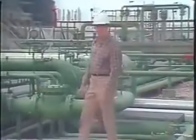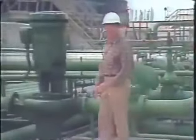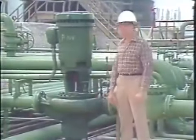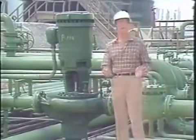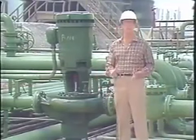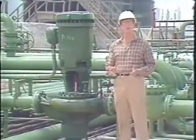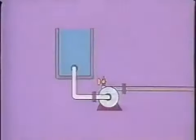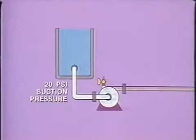Now that you know what centrifugal pumps do and how they operate, let's move on to pump priming and basic startup and shutdown procedures. First, a centrifugal pump will not operate unless the casing is filled with liquid. Before a centrifugal pump is started, it must be primed or filled with the liquid to be pumped. In most systems, there are built-in mechanisms for priming the pump. For example, if the suction supply is above atmospheric pressure, the pump may be primed by opening a vent at the top of the casing.